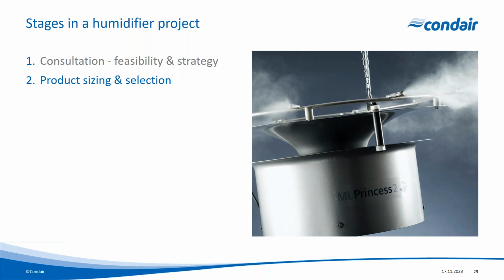So we need to size the humidification system based on the air exchange rate within the space and the external conditions and the internal conditions required. Once we have that, we can do a duty calculation and a selection. And if we're integrating into an existing HVAC application, we'll be able to then produce a selection and calculate whether we can get enough moisture into the supply air to increase the moisture content in the space to a point where the relative humidity is required.